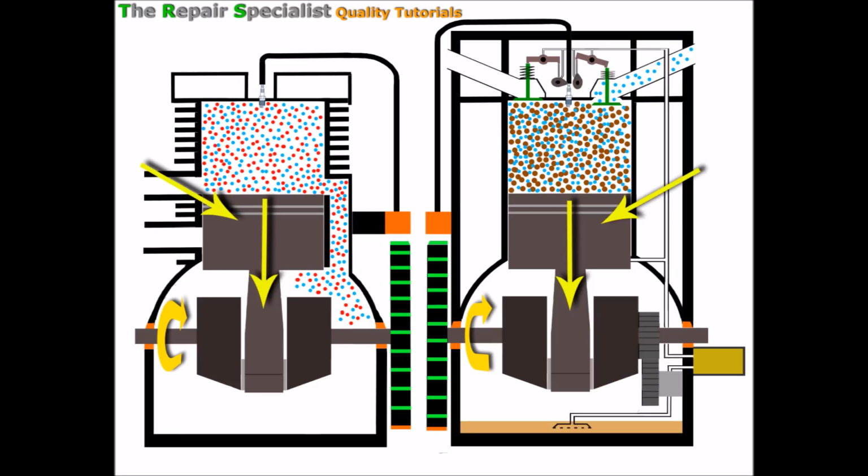Something else worth noting whilst the pistons are at the lowermost point is the magnets on the flywheel are both facing the bottom of the flywheel at the moment, which is where they should be, because when the crankshaft has turned another 180 degrees and the pistons are at their uppermost point at top dead centre, those magnets will be travelling past the coil pack. So that's a similarity for the both of them.